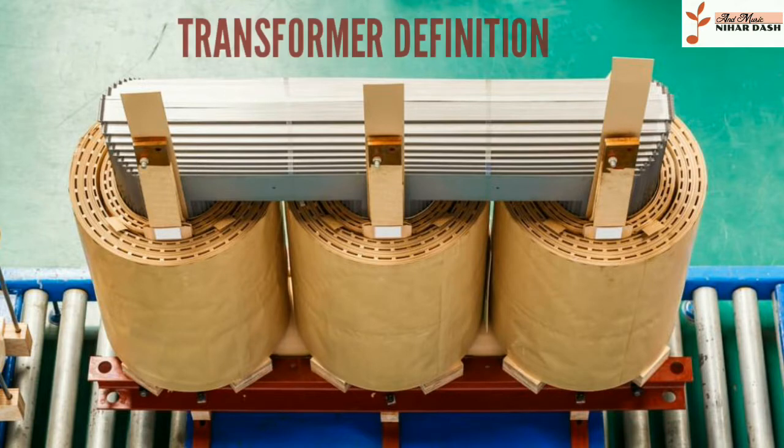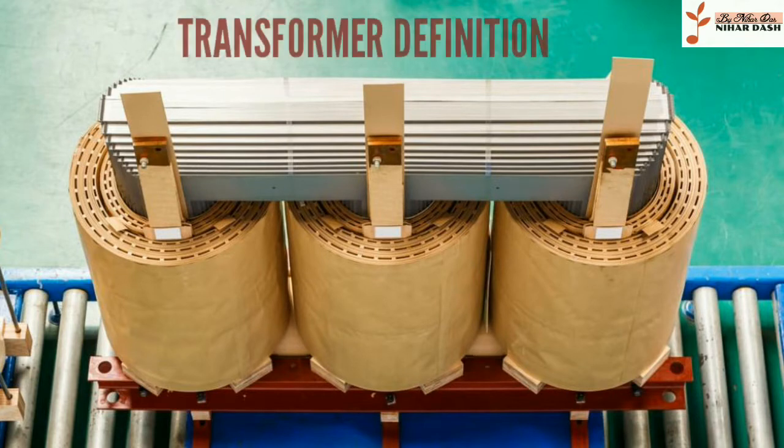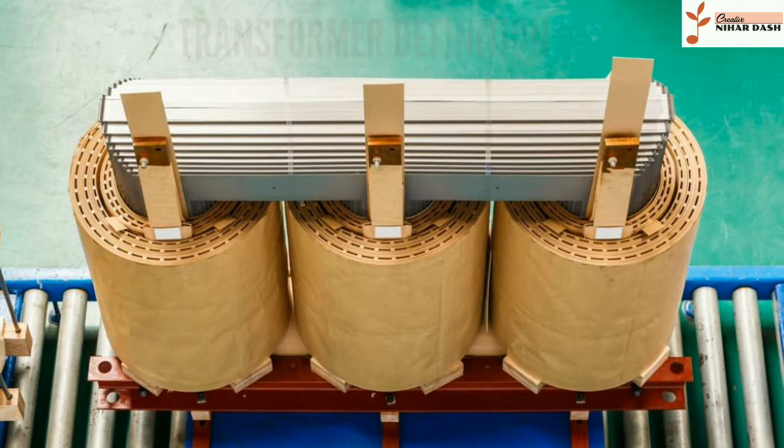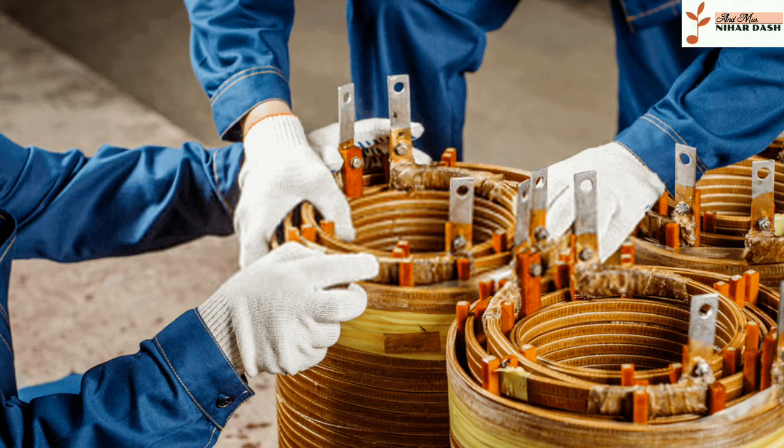Faraday's law of induction, discovered in 1831, describes the induced voltage effect in any coil due to a changing magnetic flux encircled by the coil. Transformers are most commonly used for increasing low AC voltages at high current, a step-up transformer, or decreasing high AC voltages at low current, a step-down transformer, in electric power applications, and for coupling the stages of signal processing circuits.